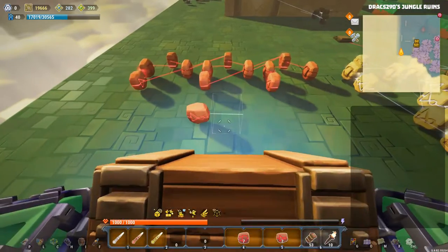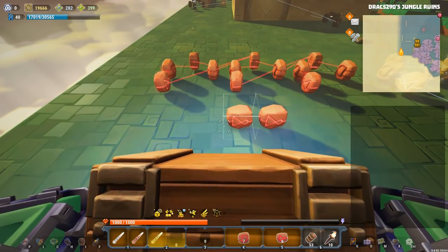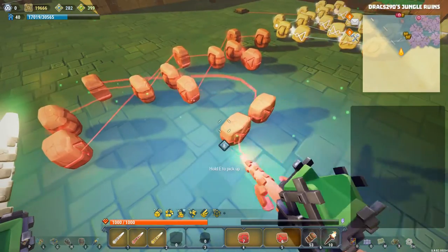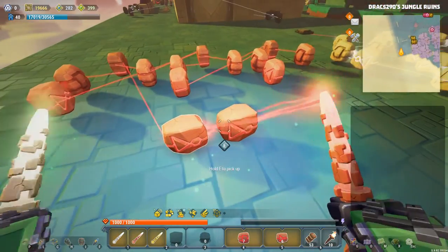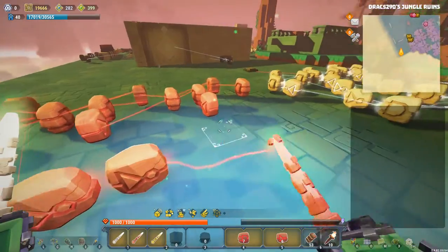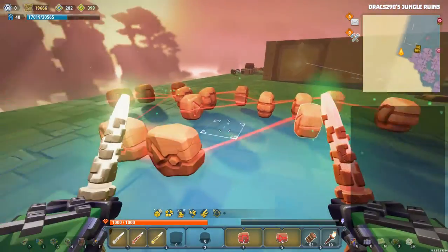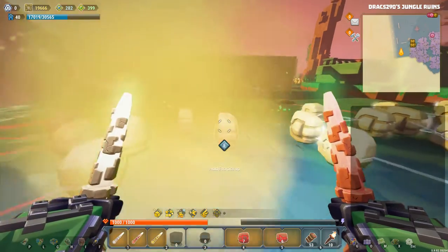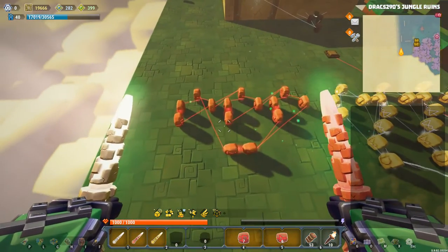Now we're going to feed back a little loop. So we're going to create a little node here, and we're going to feed back from the third. So the third is just going to go down to this node, and then we're going to connect the node to the first NOT gate, and also through to the A side of this guy over here. So there you go, that is now that little counter set up.